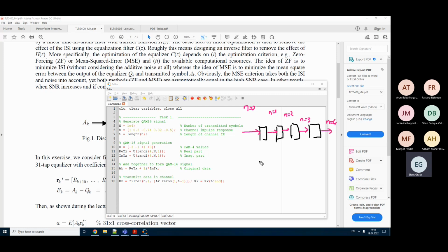Yes, so basically, we can say that here is L minus 1, and accordingly, considering that MATLAB starts numbering from 1 rather than 0, we have to add plus 1, and we get this L. And then we read all the remaining signals up to the end. So the first input value at the output of this filter will be after these 4 time delay units. That is 4 in this particular case because here I have them 4.